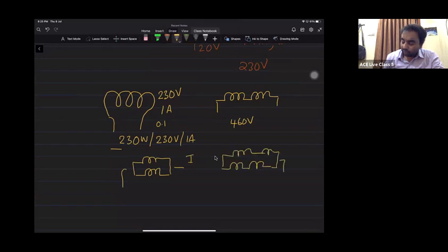This entire configuration we call a winding. So if you look into any winding of a generator or any winding of a machine, you can see the series and parallel connection of coils. In the coils, you can see there are turns. And in the turns, you can see there are conductors, and these conductors are 180 degrees apart for full pitch, right?